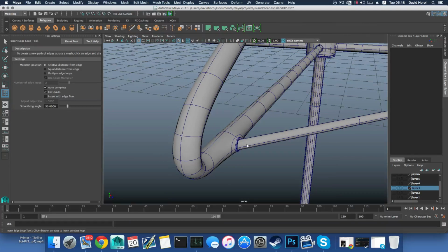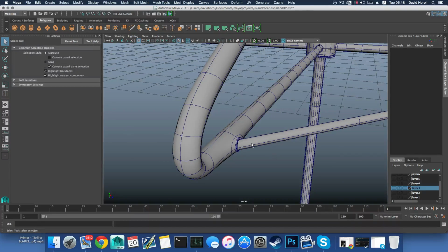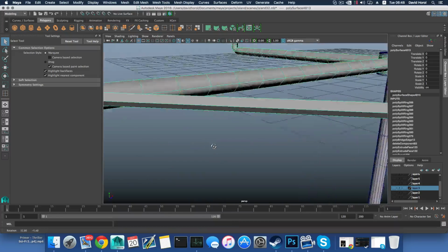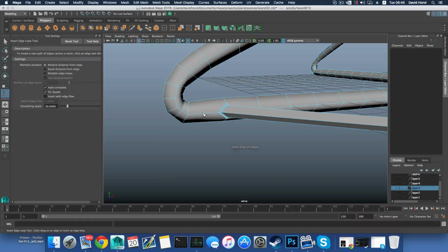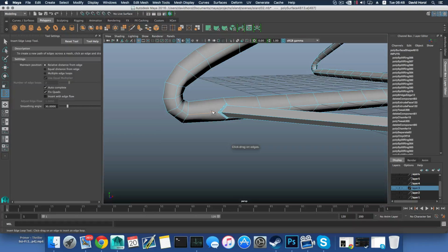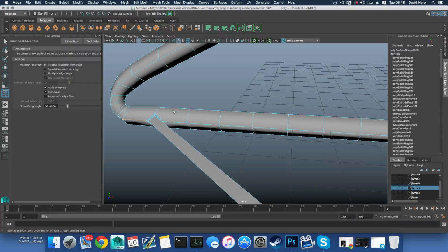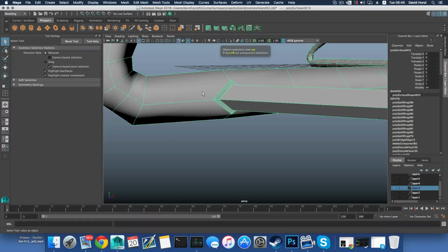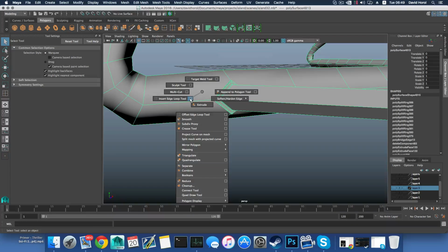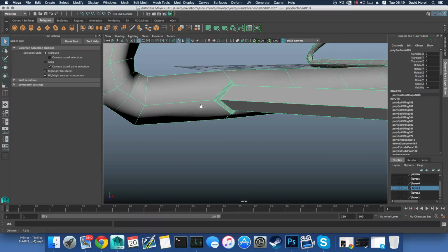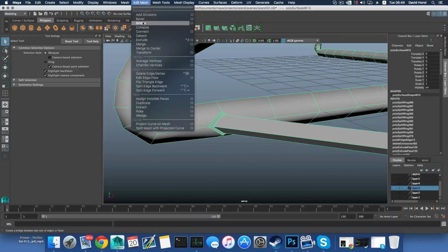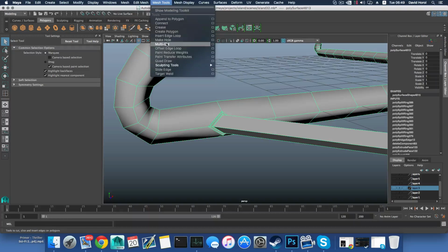Okay, yeah, that's nice, but as I'm thinking of this, the only problem I have here is that I need to add more edge loops, like one here that will constrain this area, and this one constrain. I'm not sure that this is the word. Sometimes I use words that sound like they fit into the situation. If it doesn't work for you that way, you can take the multicut tool.